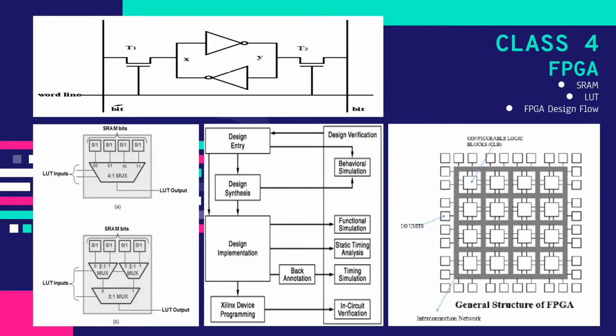Now translate combines all the input netlists and constraints to a logic design file. Now defining constraints means we are assigning the paths in the design to the physical elements like pins, switches, etc. of the targeted device and specifying time requirements of the design. This info is stored in a file named UCF, or the user constraints file.